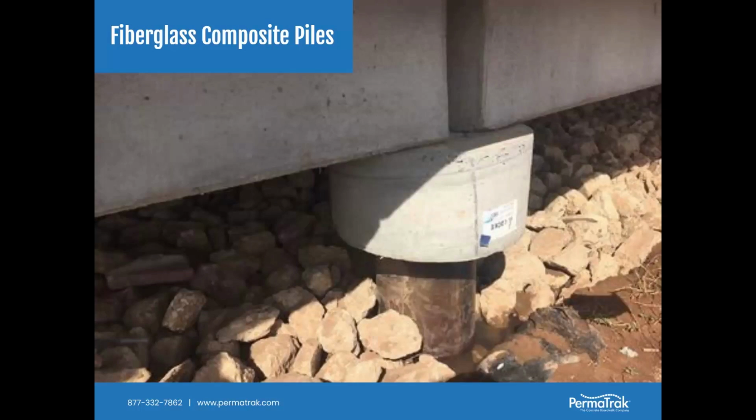Next system is a fiberglass pile. I mentioned the brown, that's a fiberglass composite pile system. There are several fiberglass suppliers who do this, and these are pile systems that started their industry in the marina environment, and they were used for bumpers at bridge piers and bollards, if you will. And now they found their way to being used as piles, and they can be driven.